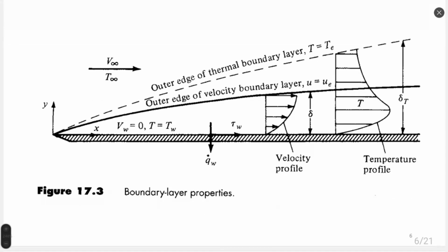Once we talk about high velocity applications, compressible flow, we can see both changes of velocity and temperature. Velocity profile determines the thickness of boundary layer, and temperature profile determines the thickness of thermal boundary layer. How do we understand the concept of thickness of boundary layer?